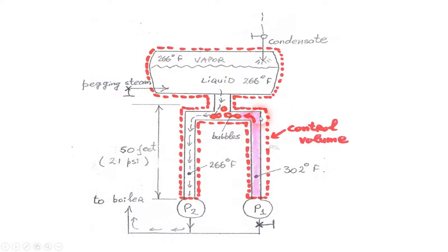The answer to that problem is that when the vapor bubbles reach the colder region, they'll have to be condensed. They will condense, as we talked about in the video. And that condensing turns them back into liquid, and therefore no vapor would reach pump number 2. There will not be enough time for these vapors to travel all this distance. They will condense into liquid sooner.